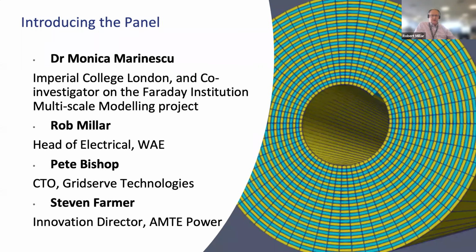We can actually start to look at what the real genuine performance of a cell is without that need to go through that testing loop and have all these convoluted procurement activities that we always have. I think the second thing that it probably gives us is, traditionally, if we were able to receive a model, it would be an equivalent circuit model of some sort, and that is much more difficult for us to interrogate. Typically, it's a black box model, and we would have difficulty in modifying that to show the through life or the degradation performance of a cell. And so that becomes a problem for us.